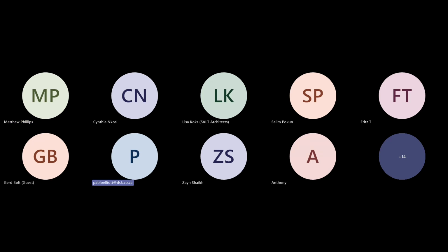Okay, so everything complies with the regulations in terms of R values. It must be said that both cork and CLT are very well insulated, cork especially. We've been living in the house for 3 years now, and we live in Newlands, which is very, very wet, and we have not had humidity at all. It's cool in summer, especially with the roof light, which encourages natural ventilation. On the northeast side, we have a roof overhang of 1 meter, which keeps summer sun out and lets winter sun in. So in winter, it's nicely warmed.